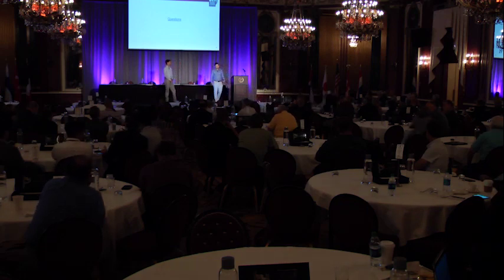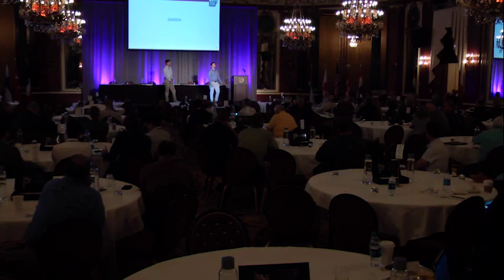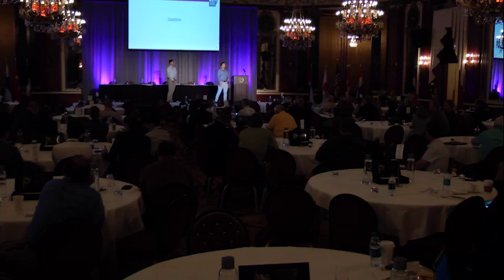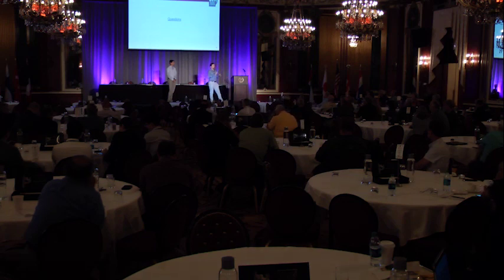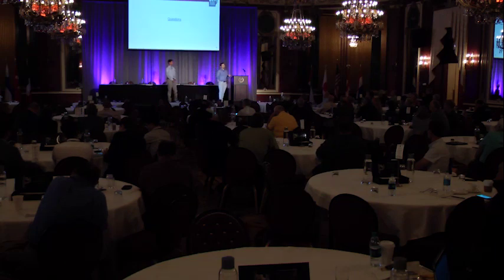It's good to understand how much of the exterior wall is being removed. For example, I worked on a Target project where it's all tilt-up wall panels. There are cases where they're just taking 20 feet out of a 300-foot wall. It's not going to be that big of a deal. But in one case, they took all 200 feet out, so we had to run cables in every single bay to prevent uplift, and we also had to provide lateral support in the case of wind loading. We didn't design for earthquake loading, but we had to essentially replace the shear wall with cables. It's just important to have that conversation up front. Sometimes you don't really need it, but if you're going into the windy season, it's definitely a good conversation to have.